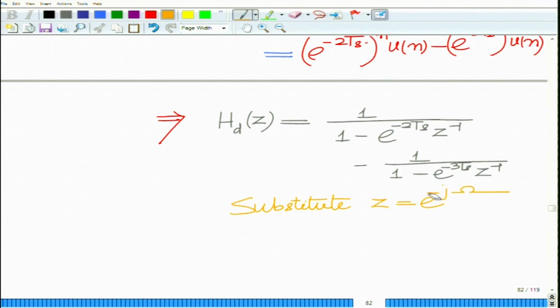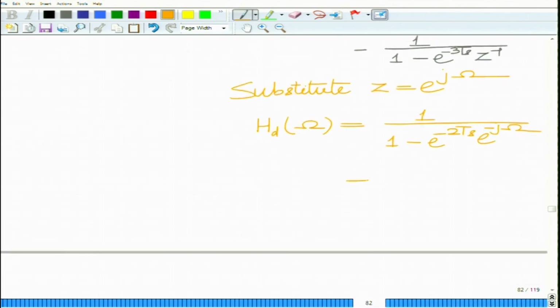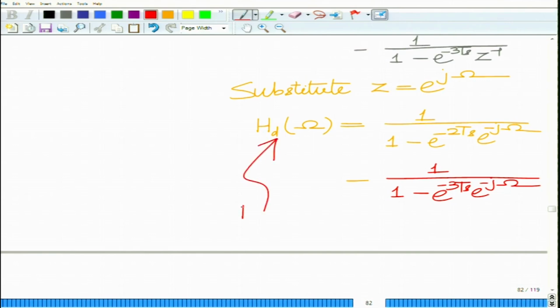Substitute Z equals e raised to j omega, and that gives us Hd of omega, which is 1 over 1 minus e raised to minus 2Ts e raised to minus j omega, minus 1 over 1 minus e raised to minus 3Ts e raised to minus j omega. Okay, so this is your DTFT.